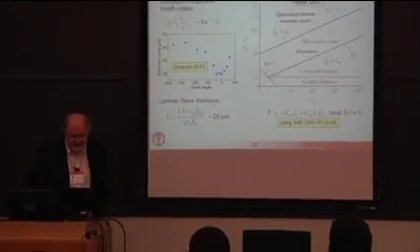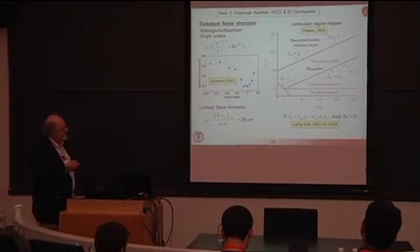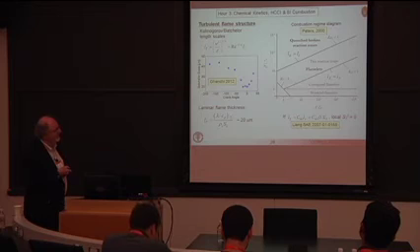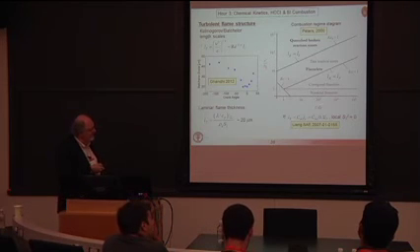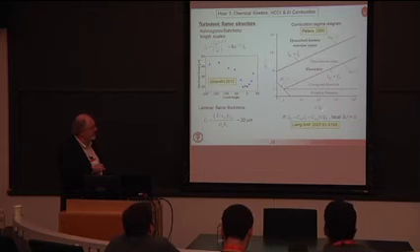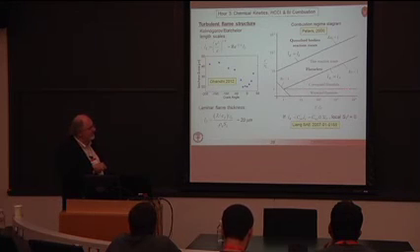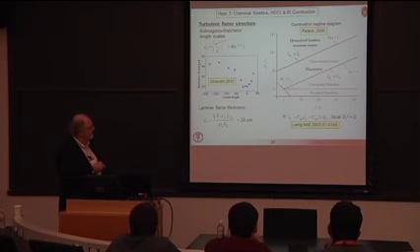Okay, just a word about turbulent flames. Here's a plot that some of you may have seen before from Norbert Peters' book, where he describes the regimes of combustion that occur in a spark ignition engine, for instance. Here's our turbulence intensity normalized by the laminar flame speed. Here's the turbulent length scale normalized by the laminar flame thickness. And as you can see, there are regimes that go from just having a laminar flame that is wrinkled by the turbulence all the way to the turbulence breaking up the flame and essentially quenching the flame.